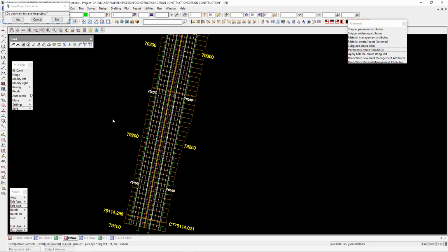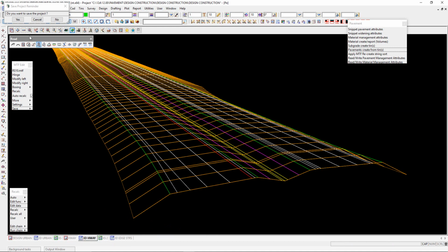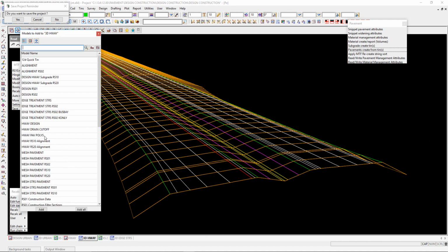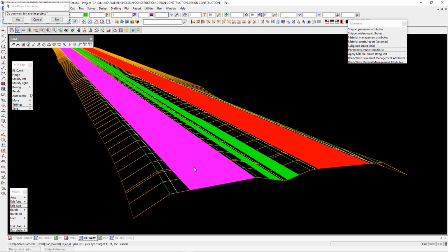So if we have a look at our job here, or back in our perspective view possibly, and we look at our highway pavement polygons. So there the polygons created. Said that having nice continuous strings gives us some good polygons. So we can look at the pavement applied to a coloured tin and have different pavements depending on what profile. In this case here, we're just doing a grass profile in that particular road.